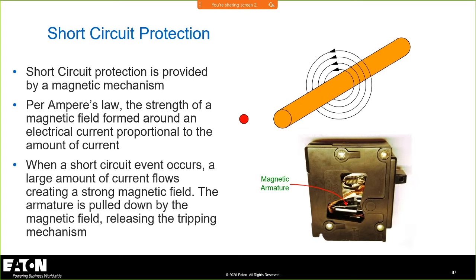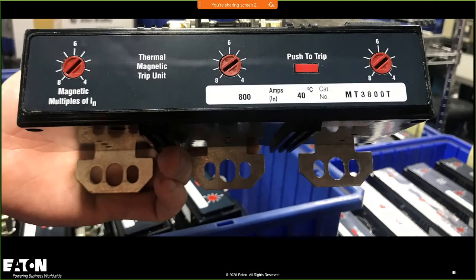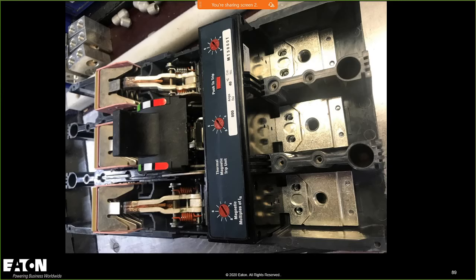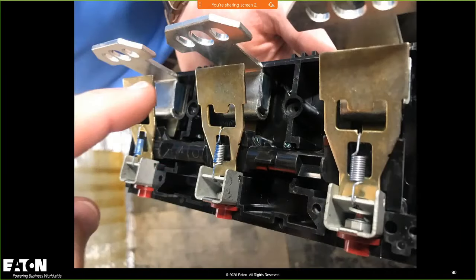Now on the larger breakers, to show you that I'm not all that crazy, this is sort of a thermomagnetic trip unit that you might see on a larger breaker. This is an 800 amp breaker, and you'll see there's 3 dials on the face of this device that controls the instantaneous pickup of that breaker. This is what it looks like inside of a breaker before it's closed up. That's where it sits, just below the handle.